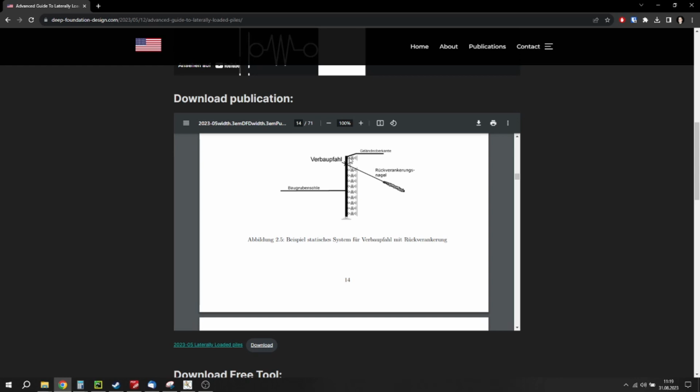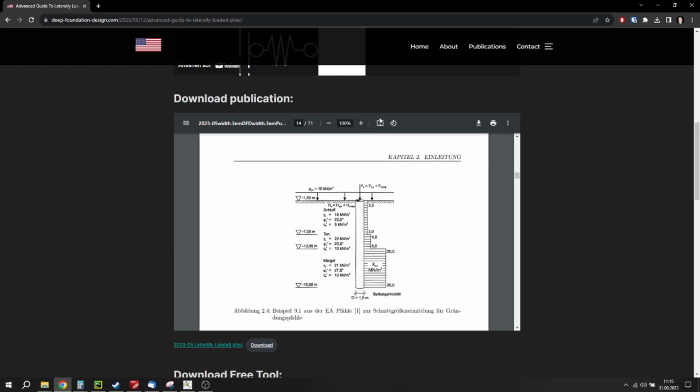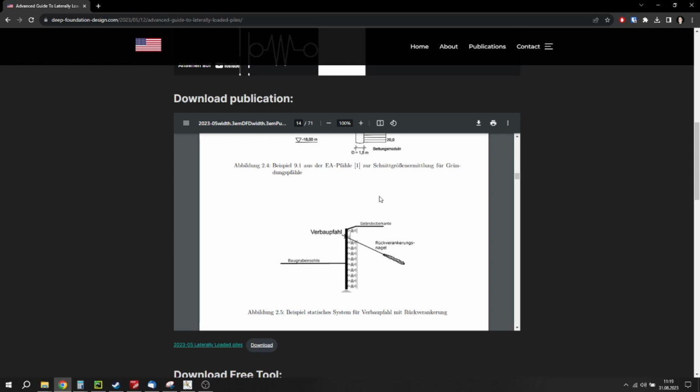However, for the rest of the pile, in the areas where you have active earth pressure that is going to be loading the pile from the side, and also with the limited deformation that you have to consider of this nail that is basically keeping the pile anchored in the surrounding soils, this is a more sophisticated sort of calculation that you would have to do. And for a calculation like this, you cannot really use this method well. And there aren't really methods to do these things.